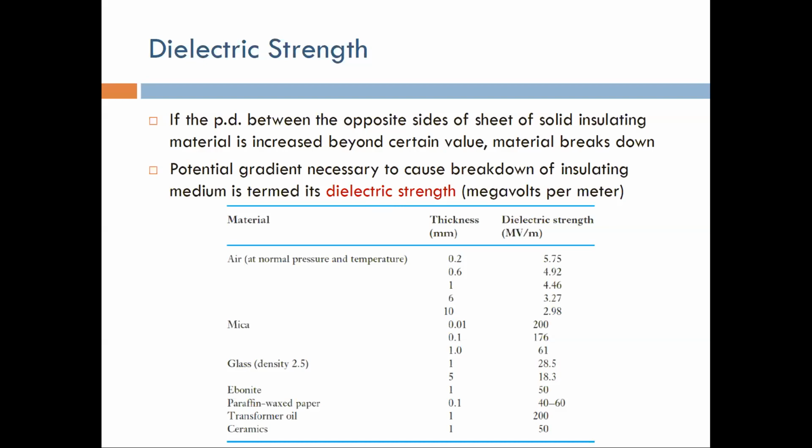What's going to happen is much more catastrophic, because usually these currents will be very high, and when you flow a very high current through a material that originally has very high resistance, you will generate enough heat to burn that particular capacitor. This is one of the causes of what we saw in the videos. So we have to make sure that we don't exceed the rated voltage, because you don't want that to happen.